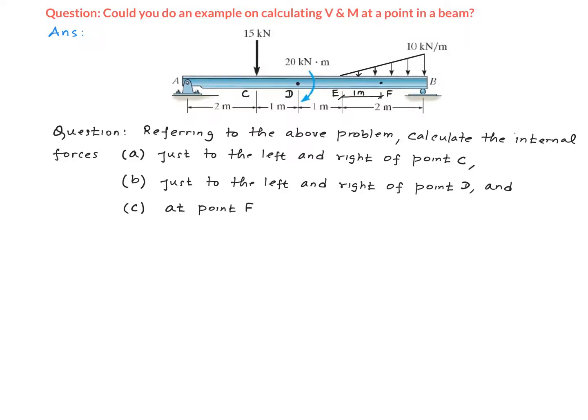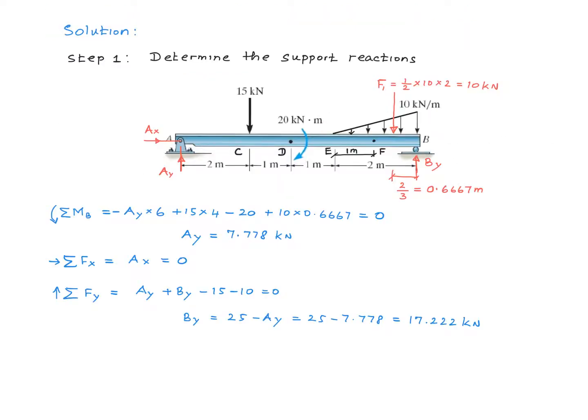load. Also, one has to be especially careful about calculating the internal forces below a point load, concentrated moment, or at a point within a distributed load. So I have intentionally chosen those points here. First step is to find the support reactions.